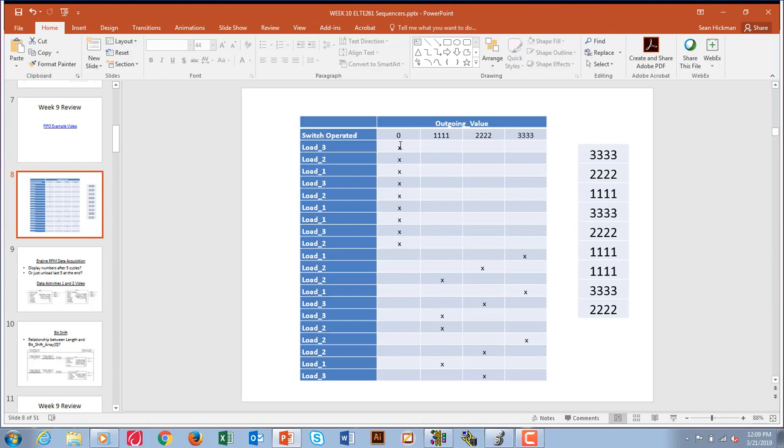So the first 9, all this did was load up the array, at which point we got that done bit to come on, which allowed us to not only load it, continue to load it, but then to unload it every time we push the button. So when we finally got around to unloading it, the first thing that got unloaded was a 333 right here. What number is that? It's this one right here, because this was the first one that we put into the array, and therefore it is the first one out, because we did first in, first out.